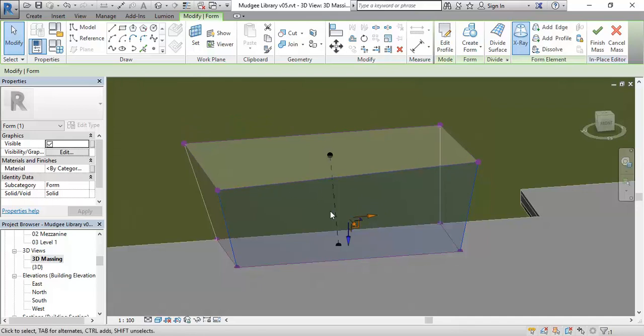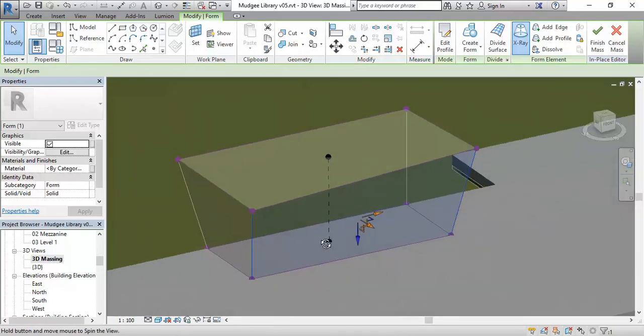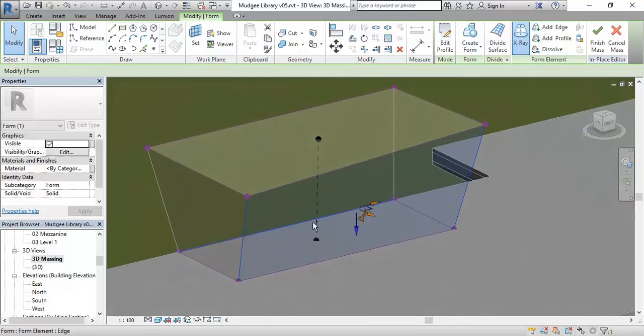This one especially you can see has the same angle as that surface. That can be useful, but it's often not what you want, and you want to go back to just straight X, Y, Z. To do that, there's a shortcut: spacebar. That makes them, again, RGB, red, green, blue, which means X, Y, Z. So space toggles between those two options.